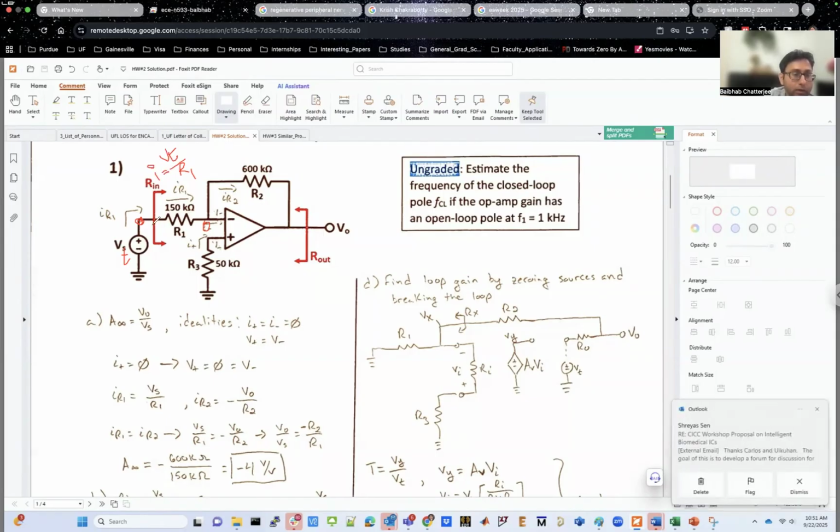Now, the ratio of the voltage on the left side of that R1 resistance to the current flowing through it will be the resistance seen at the input side, according to Ohm's law once again, because voltage divided by current is your resistance. So VT over I is going to be VT divided by VT over R1. So your Rin is actually going to be R1. What the resistance that you see looking into this particular port is going to be exactly equal to R1.